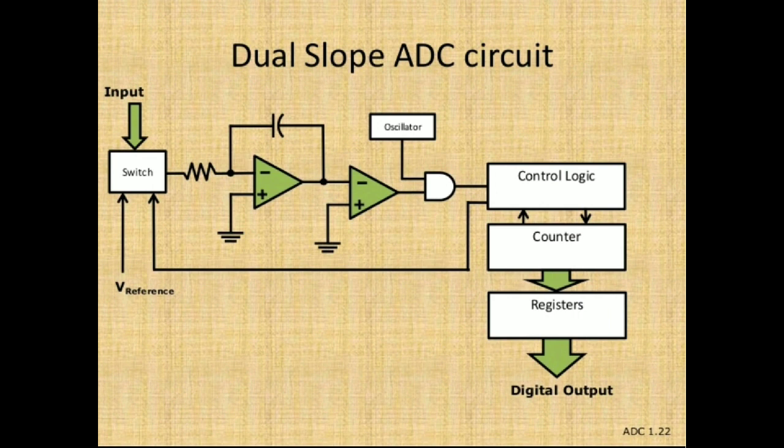So say for example the second comparator output is 1. Then the oscillator continuously generates clock pulses, which are multiplied with the other terminal, that is 1, so the AND gate output will be the clock pulse. The AND gate function is to multiply the two input signals, so the AND gate output will be the clock pulse. A continuous clock will be generated in the positive manner. That is why a positive going ramp is produced.